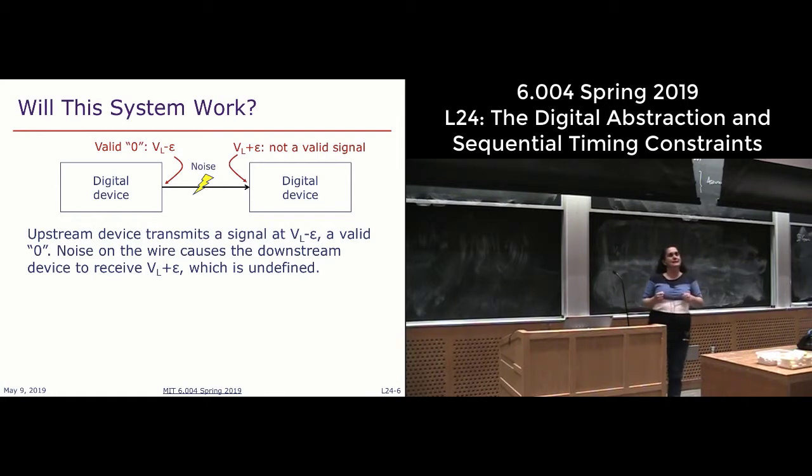And so this next circuit sees, instead of voltage low minus epsilon, voltage low plus epsilon. Now I've put myself in kind of the same problem I had initially of confusing zeros and ones, except in this case, I won't confuse it to be a 1, but I might think that this is an invalid input, okay?